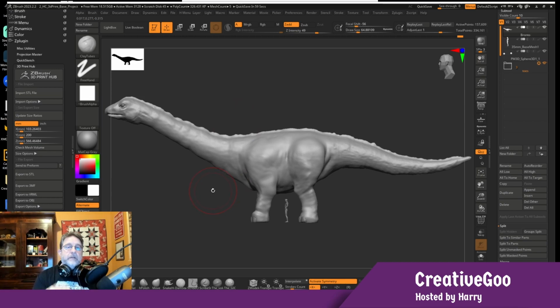But anyway, this model is 55 centimeters in one direction. And if your printer can't handle that, you have to know. So you need to know the dimensions of the model. Even though everything else about this model is printable, in fact, it's a very simple model, it's too big. And so as the modeler, I might have to cut it into pieces. It's very doable. Software makes that easy. I can even register it so that there's a peg on one side and a hole on the other. But you have to know before you export it. Otherwise, you end up with an unprintable STL file because it's too big for most people's printers.